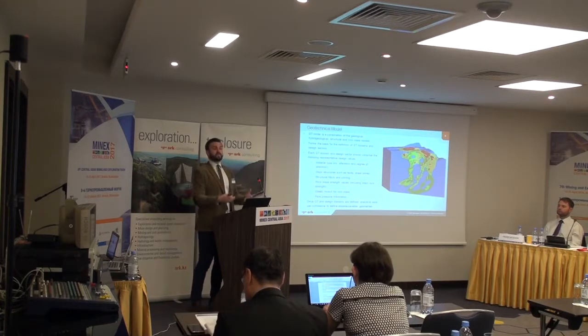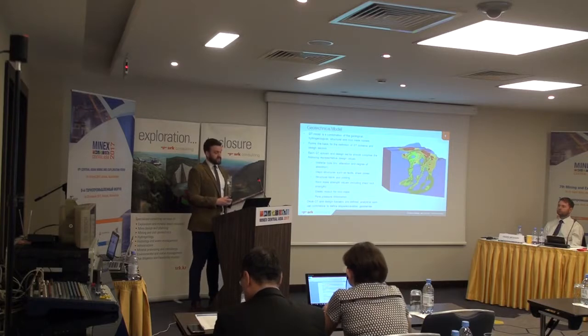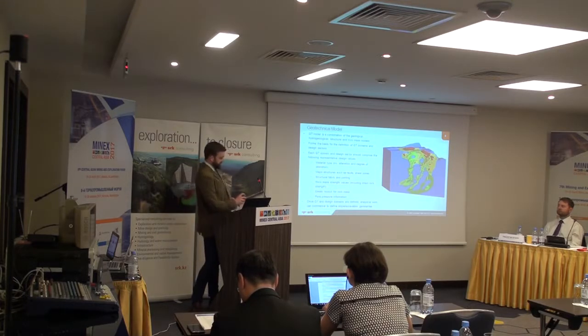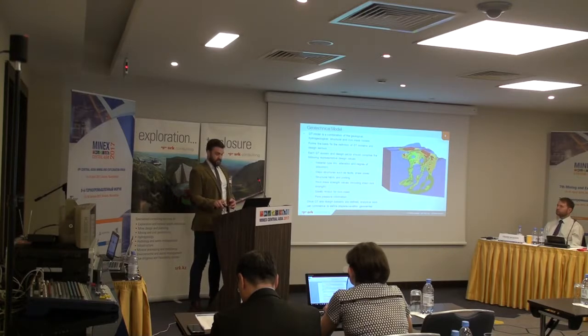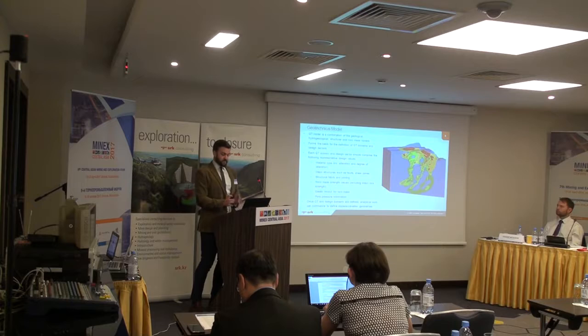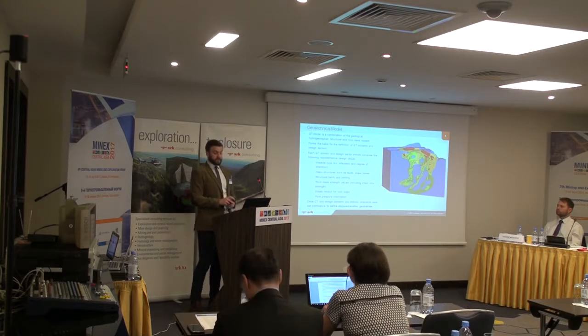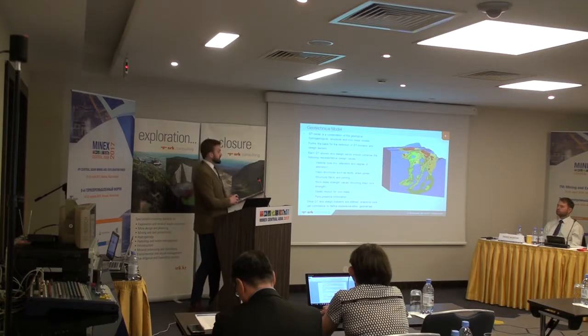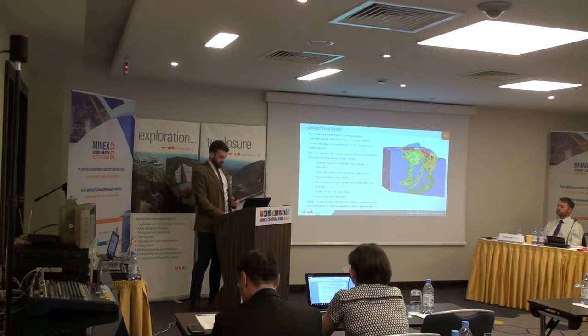And so once you've developed that geotechnical model, it's really then that you can undertake your slope design or your underground mine design. And this image here is just an open pit where we have carried out some state-of-the-art Leapfrog modelling to define some of the areas where we have poorer rock mass conditions in comparison to the surrounding waste material.